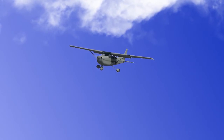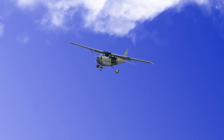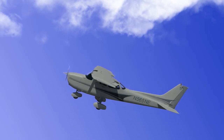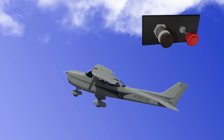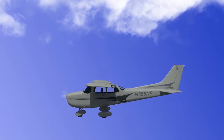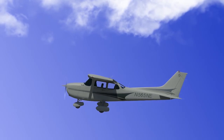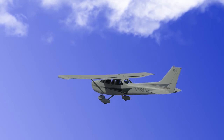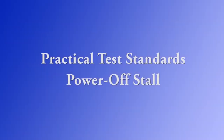As the stall develops, you will feel the vibration or the buffet on the wings. Once you feel a buffet, the pilot should immediately start the recovery process. This is done by applying full throttle and decreasing the pitch by allowing the nose to drop. Try to hold this altitude so that the plane can gain airspeed and achieve a positive rate of climb. At this point, you will want to retract the flaps and gear if applicable, or as they say, clean up the plane.